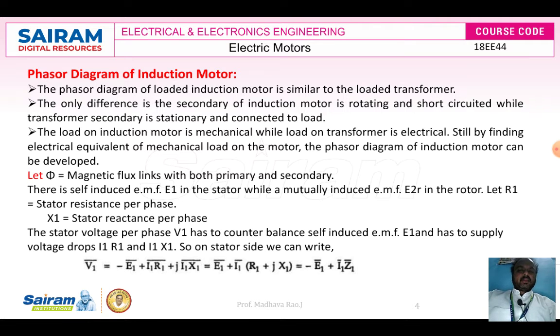The load on the induction motor is mechanical while the load on the transformer is electrical. Still, by finding the electrical equivalent of the mechanical load on the motor, the phasor diagram of the induction motor can be developed.